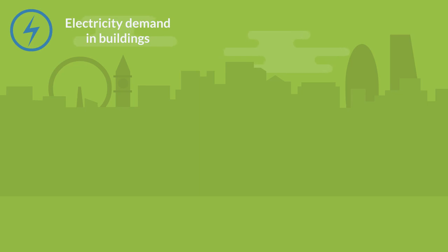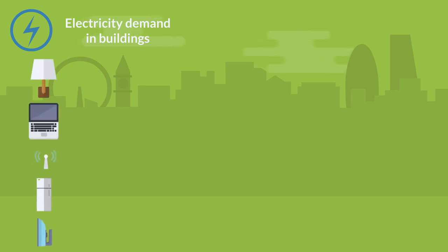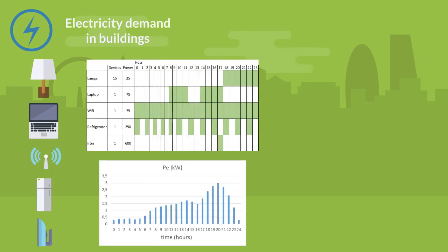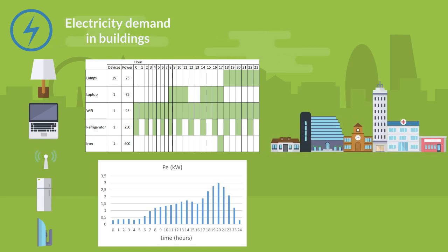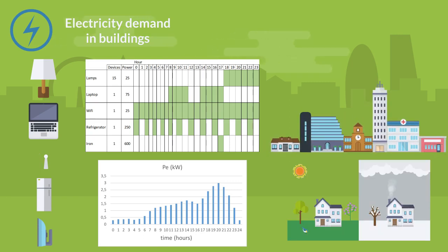Wrapping up. Electricity consumption or energy consumption depends on the equipment consuming electricity, their power, and the time they are consuming electricity. Using a spreadsheet, you can easily calculate the daily consumption curves, which depend on the utilization of the building and the climate conditions if air conditioning equipment consumes electricity. Curve peaks will allow you to calculate the power to be installed.